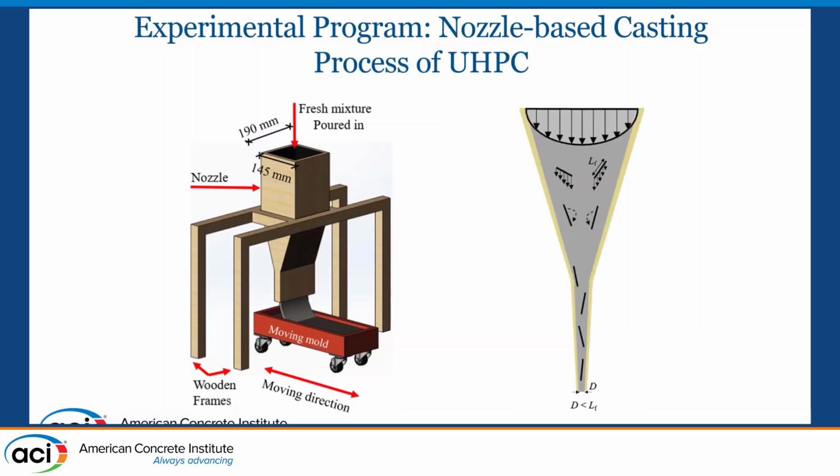The main mechanism is you create a convergent flow, and after that you add another small contraction where the exit of the nozzle has a characteristic size less than the fiber length. So even if you have some fibers which are not oriented, you force them to be oriented by inducing this dimension. That was the main hypothesis or rationale behind making this kind of nozzle.